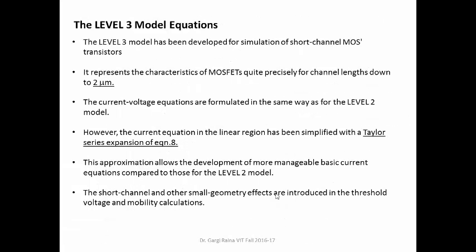Next we come to the level 3 model equations. The level 3 model has been developed for simulation of short channel MOS transistors, and it represents the characteristics of the MOSFET for channel lengths down to 2 microns.